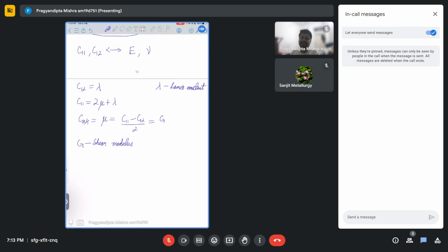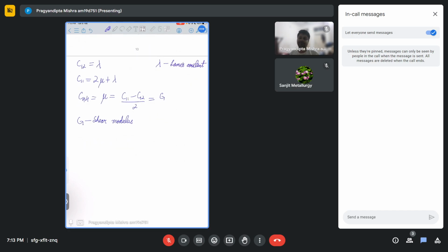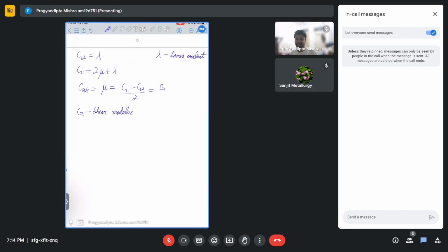Using this, you can also derive the relation between your various moduli of elasticity. For instance, if I want to know the relation between shear modulus and E, I can write G is equal to E divided by 2 times (1 plus nu). This is one relation. Similarly, if I want to know the relation between bulk modulus and modulus of elasticity, I can write K to be equal to E divided by 1 minus 3 times...